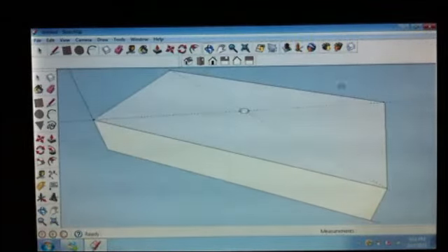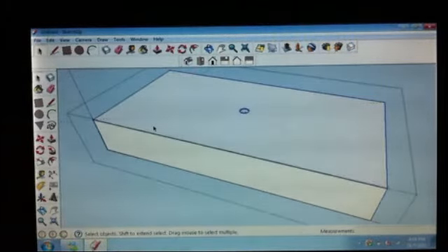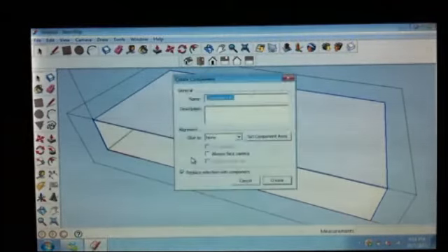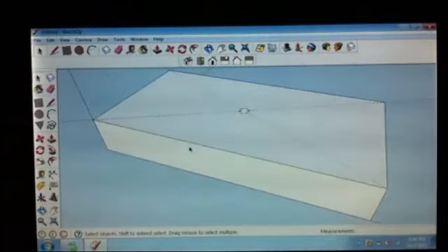Now you're going to make a rod that passes through this hole here. How do you do that? Similarly, you need a circle. Let me check whether it is in. No, it's not yet. You have to make sure that you create a component. If not, later you will stick onto it and then you really can't work on it anymore.